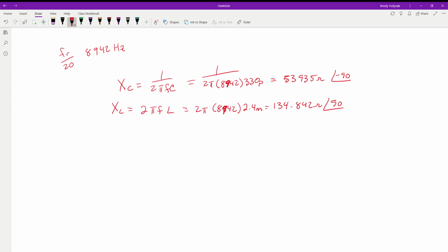Right, so now we're going to convert this into the impedance of our inductor. So it's going to be the 132 ohms of winding resistance. For that equation, we're going to convert that into polar. So give me just a minute while I chug that through my calculator.